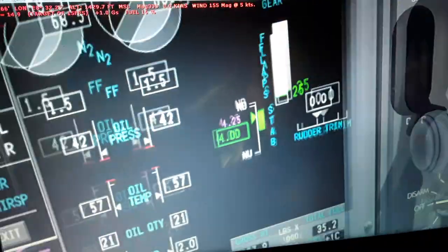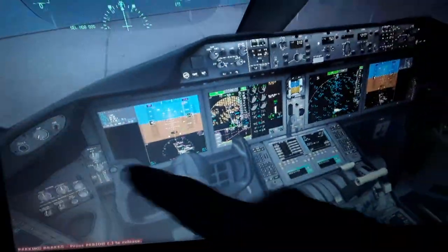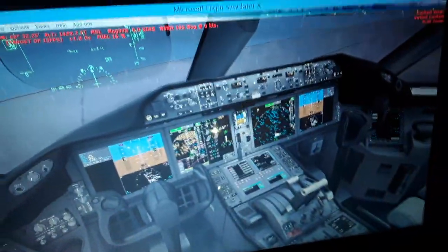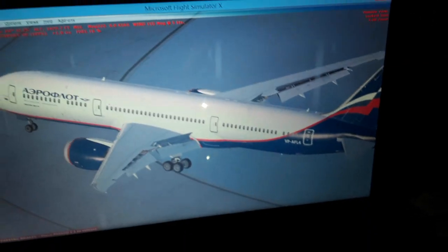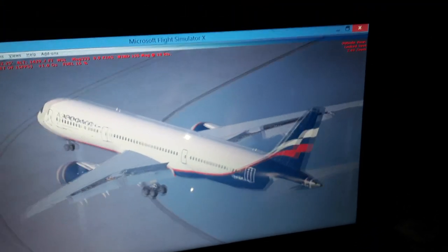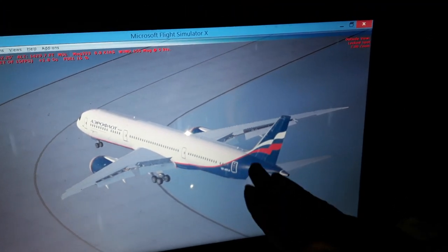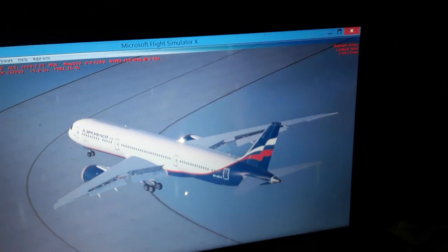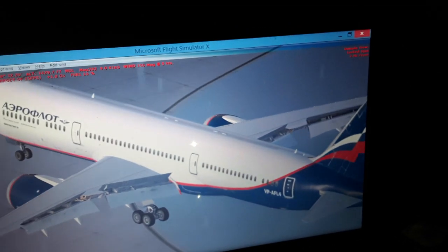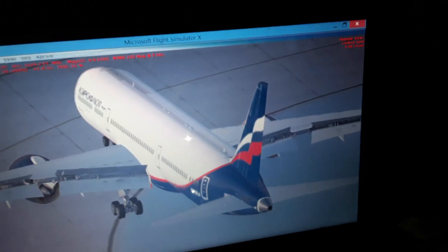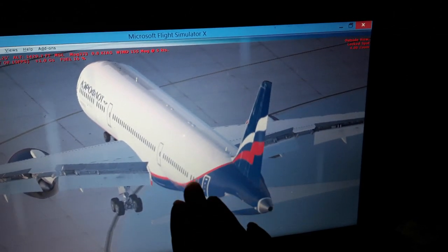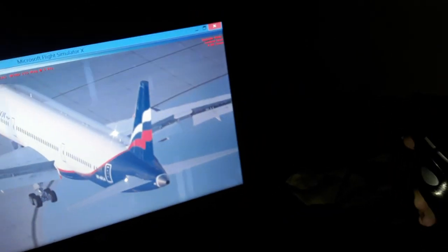So we have the stabilizer trim position here. So this will move outside, you will see, in flight or on the ground, doesn't matter. The horizontal tail we need in flight, up or down the whole surface. It will be trimmed in a position up or down in flight. So you can use also the elevator like this for climb and descent without the trim.